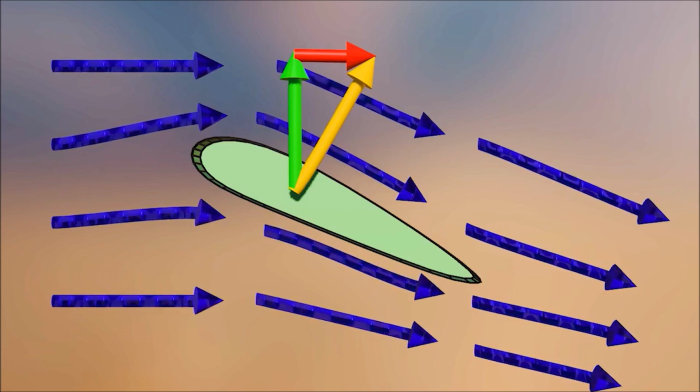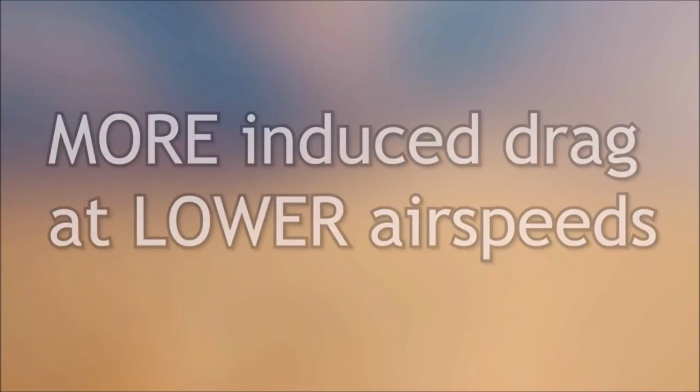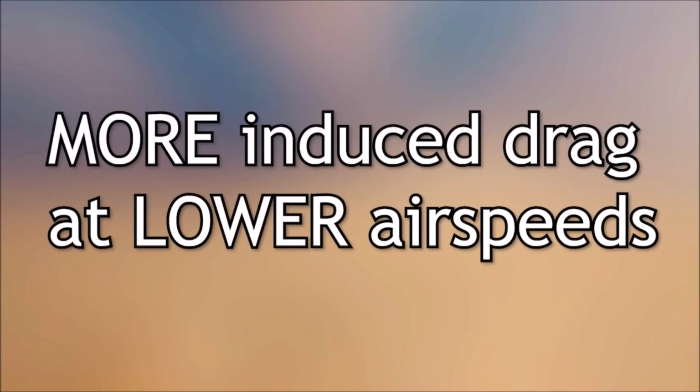This is a bit counterintuitive, so it's worth taking a minute to think about. All things being equal, we get more induced drag at lower airspeeds. This is important because we operate at low speeds during takeoff and landing, and induced drag can play an important role during these phases of flight.